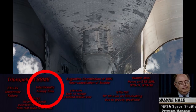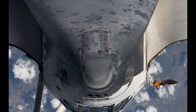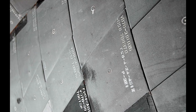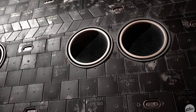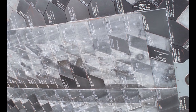Intentionally bumpy tiles. Didn't know about this. Early in the program's history, a number of the tiles on the shuttle's body were intentionally warped or uneven or otherwise disfigured. This was done intentionally in order to observe the different effects of re-entry on these tiles and evaluate the overall shield for changes and improvements. What all of this testing ended up concluding was that, overall, the tiles needed to be almost completely flat to maximize their benefits during re-entry.